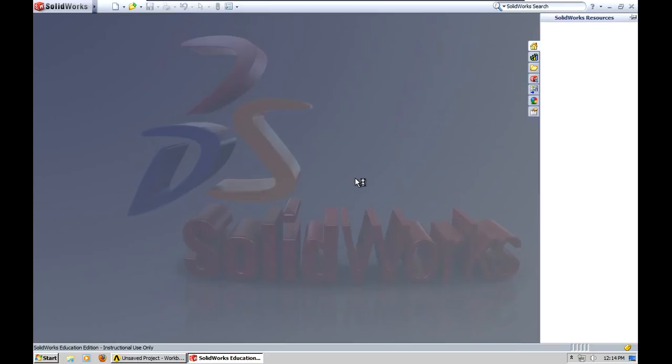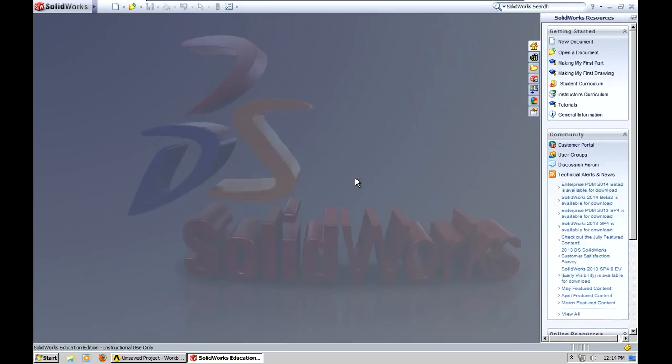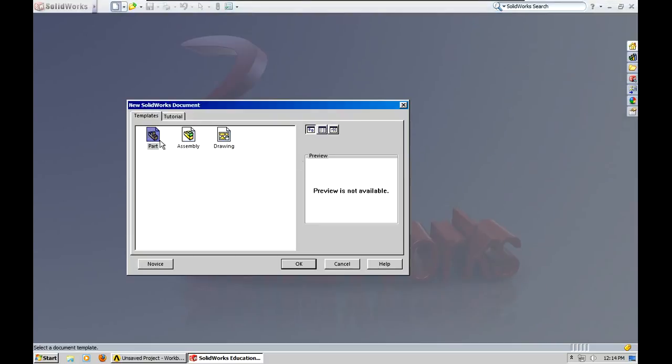Anyways, you'll import the actual physical metal gas combustor model into Workbench, and what you're going to want to do is fill it, not fill at the edges, but fill it with the fluid. I'll try to show it to you later on.